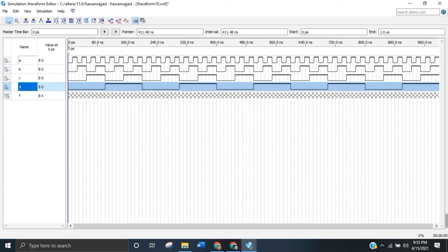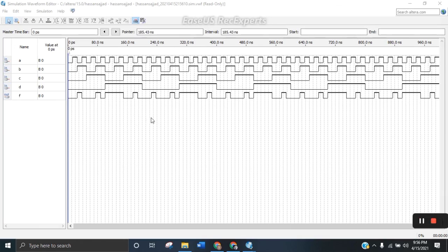So here the logic states will be like this, because when you are making the truth table for four logic states, 2 raised to power 4, 16 possible combinations will appear. When you see the wave completing a full cycle from here to here, in this area you will see the 16 possible combinations of these four waves. After that, compile it, and output like this will appear here.